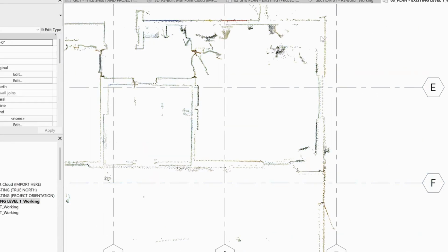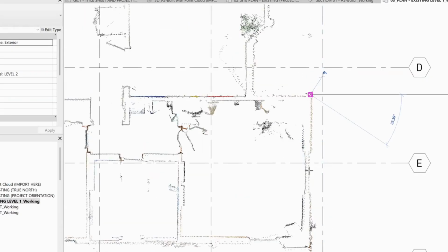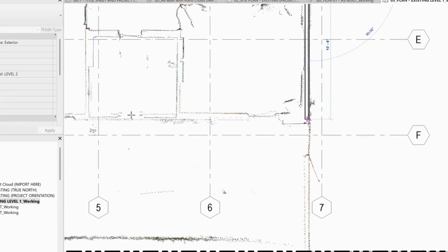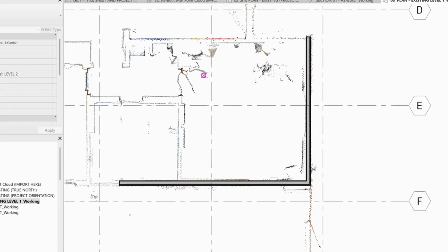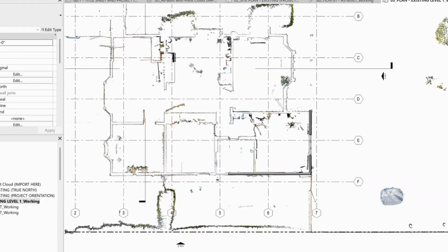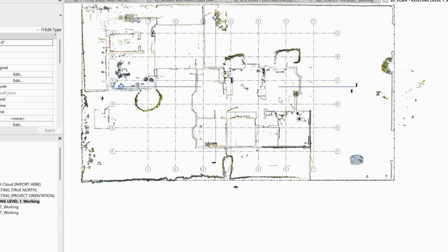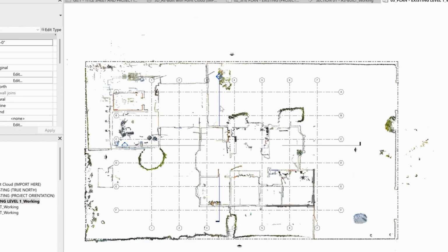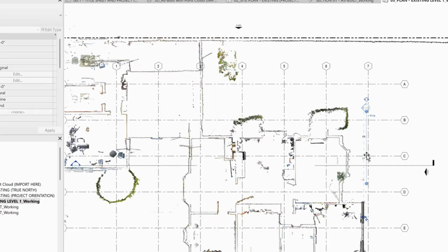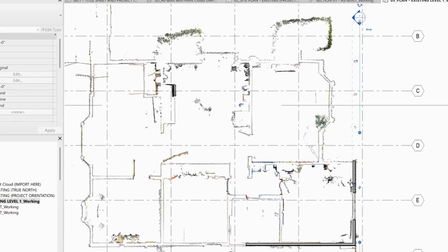And essentially, based on this, you can just start drawing walls. So, here's a wall. I'm going to pick a random wall, an exterior wall with stucco, and I'm just going to draw a wall right here. Here, and then it turns here, and I can move things around. And then I know for a fact that there's a window somewhere in this location, roughly. And that's why I say this could be a very time-consuming process. I'll take this here. I'll place it in front of this window, make it a little bit deeper.